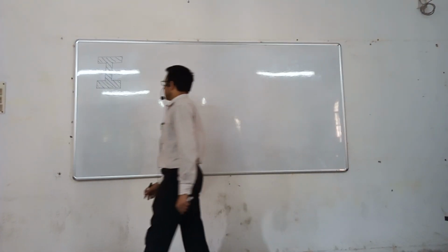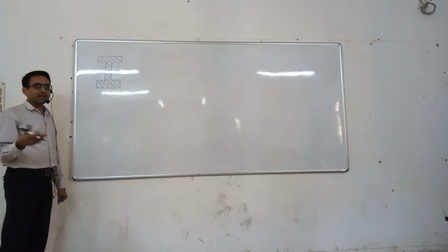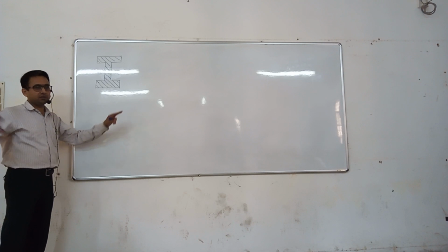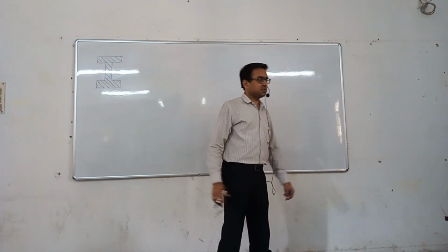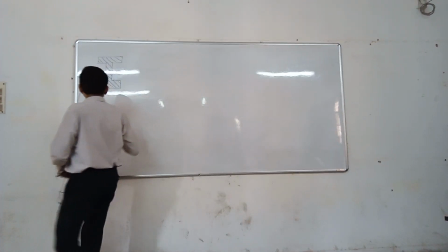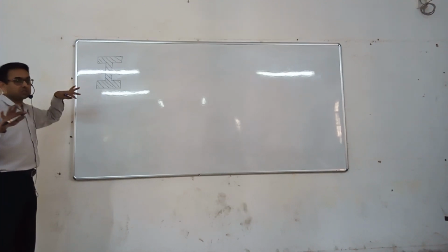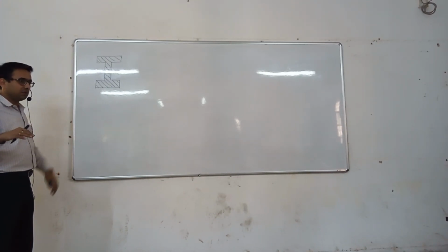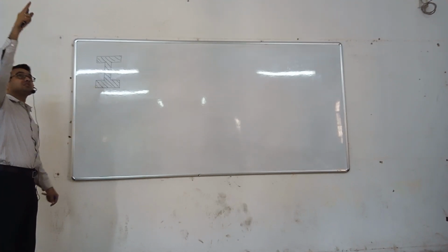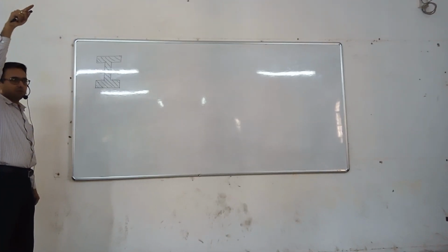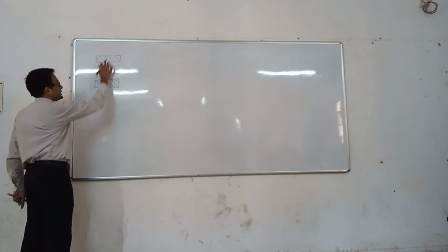Okay. So you see, I have to determine I because this is necessary for calculation of, say, bending moment diagram, bending stress, etc. These are all area moment of inertia that we are calculating, not mass moment of inertia. This is not under rotation. This is under bending because beams are under bending. This is the same simple I section, not having these top and bottom flanges.